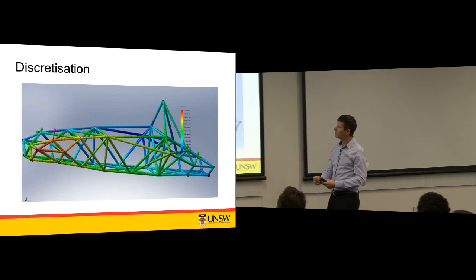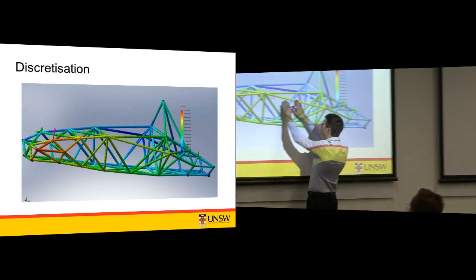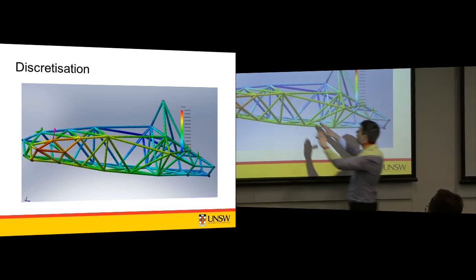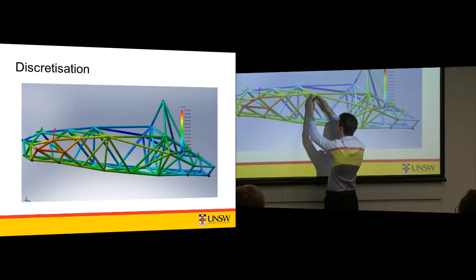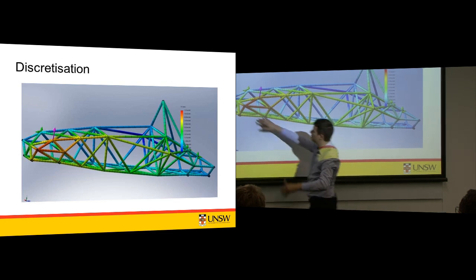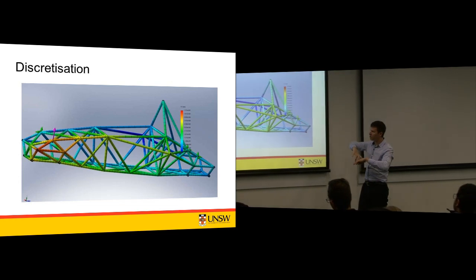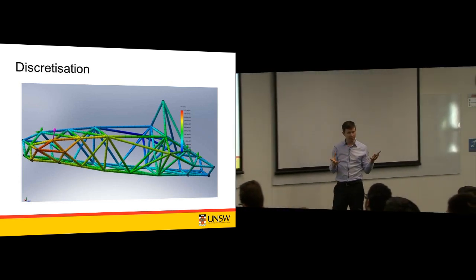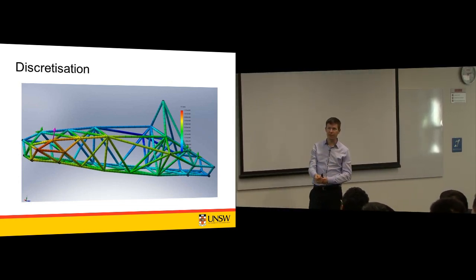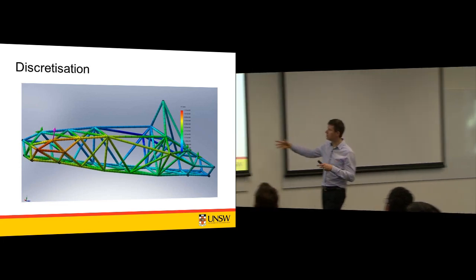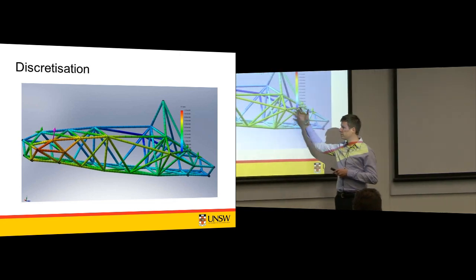And then if I could do that and define some equations to say what that state will be, and if I could do that for every little chunk, and then impose my loads on some pieces and supports on other pieces, then I could solve that all at the same time in one ridiculously large simultaneous equation. That's actually what we do. And that would tell me what each piece is doing structurally.